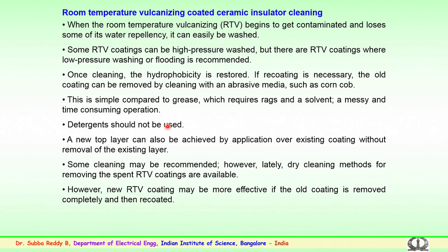Room temperature vulcanized coating. We have heard about RTV coatings on the insulator surface for better performance. The cleaning of these RTV coatings is also important, as they begin to get contaminated and lose some of their water repellency. These RTV coatings are basically coated on the insulators so that hydrophobicity is restored over a period of time. This could lose its properties and a proper cleaning mechanism has to be made.